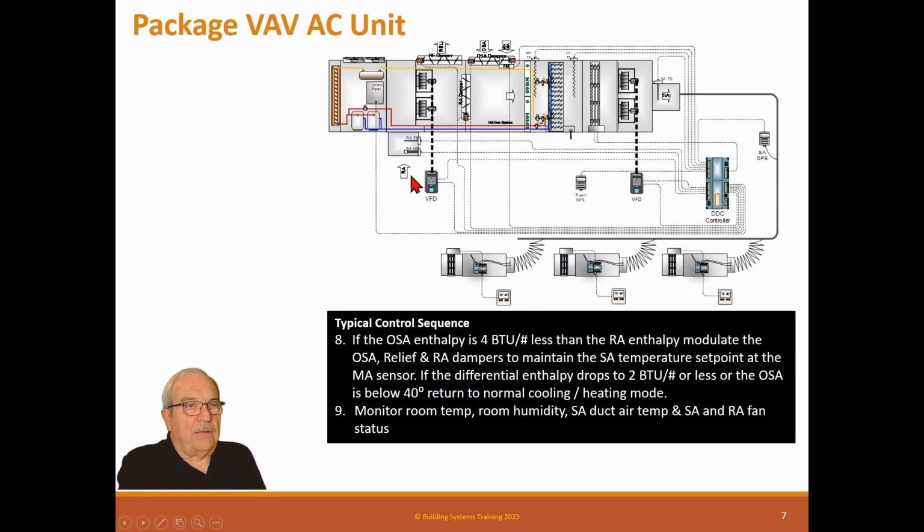The only problem we've ever had with these is that humidity sensors get out of calibration much, much quicker than a temperature sensor. And the problem is commercial building owners do not calibrate their sensors. In an industrial project where we have a process, we may calibrate the sensors every quarter, and so basically they're watching those a lot. Of course, they're much more delicate, much more expensive and much more accurate sensors, but we're keeping them well calibrated. But in these commercial buildings, no one goes up to calibrate their sensors, which they should, but they don't. At minimum, they should calibrate them every single year, and in some cases maybe every 6 months.